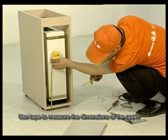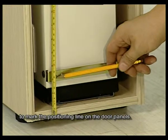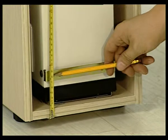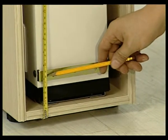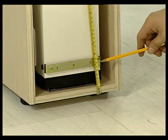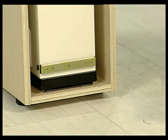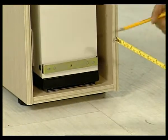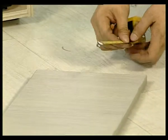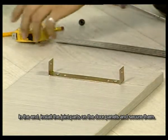Use tape to measure the dimensions of the upper and lower jointers and use this dimension to mark the positioning line on the door panels. In the end, install the joint parts on the door panels and secure them.